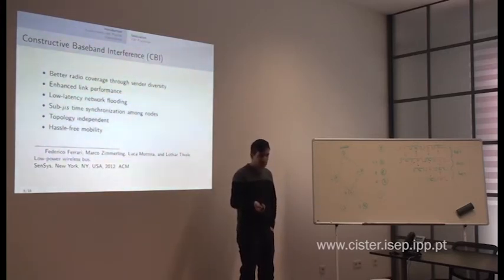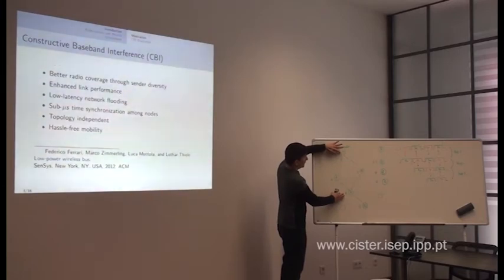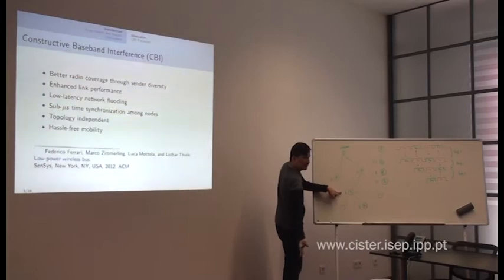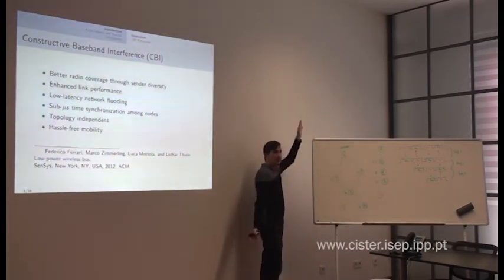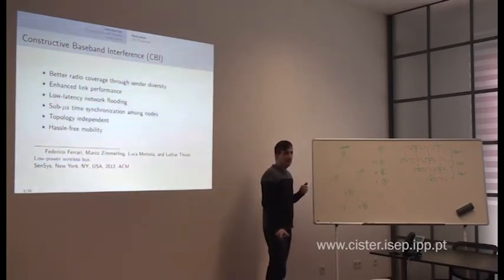Assuming that condition holds, when this node transmits, it listens to the packet and quickly broadcasts, and then you see it is not only here back where the traffic initiated, but also here in the next hop. Let's say this node here is not within the radio coverage of the first hop. So we have this sequence: as soon as these nodes start repeating, the message starts to advance through the network. You can imagine a network with a large radius where this wave of information just propagates through.